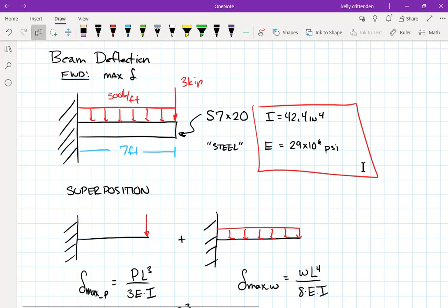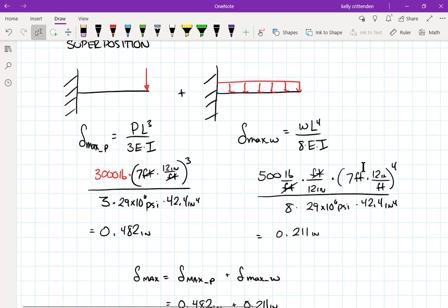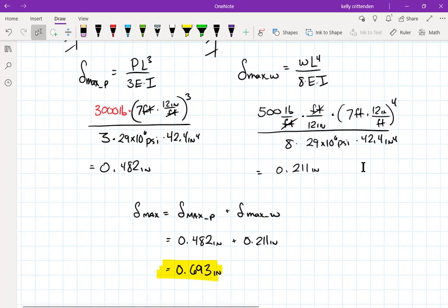The yield strength for steel starts around 36,000 psi. So you'd be really close to yielding this beam to make it do this. So you'd have very little factor of safety. Your factor of safety would be like 1.2 or 1.01, or it wouldn't be a lot. I don't know what it would actually be. 36,000 divided by 1.01 or 1.09.